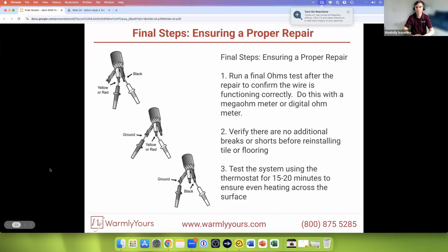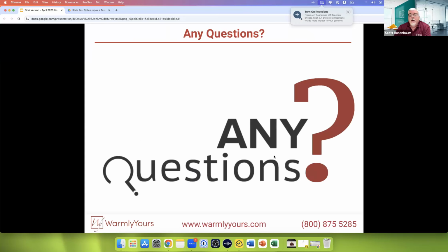Yep, and if you want to run it, because that way you can check the GFCI, you can let it run for a little while. Never let it run overnight uncovered. You can let it run for 15, 20 minutes uncovered, but that's it. Cover the repair, and then you can run it later, but you're going to need to finish up there.